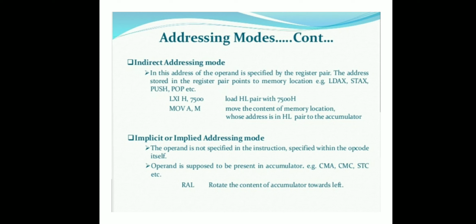It means after execution of CMA, the content of the accumulator is complemented. CMC, complement carry, and STC, set carry, are also used as implicit or implied addressing mode.